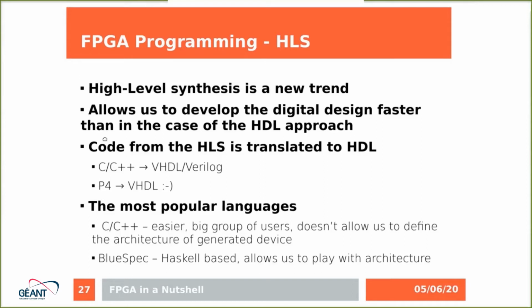So very typically we have high-level synthesis tools from C or C++. This code is then translated to VHDL or Verilog. It depends on the tool, but we can also have a compiler from the P4 language to VHDL, which translates the P4 code.